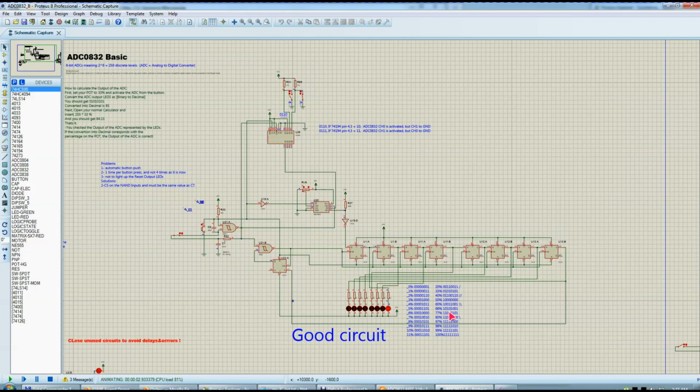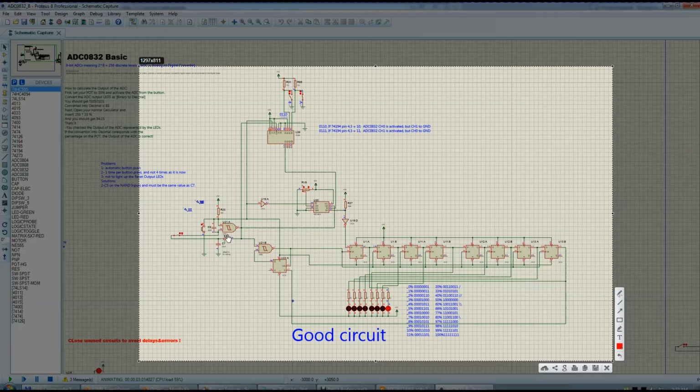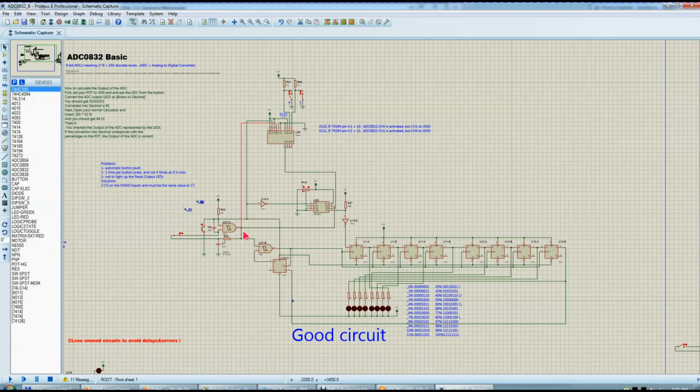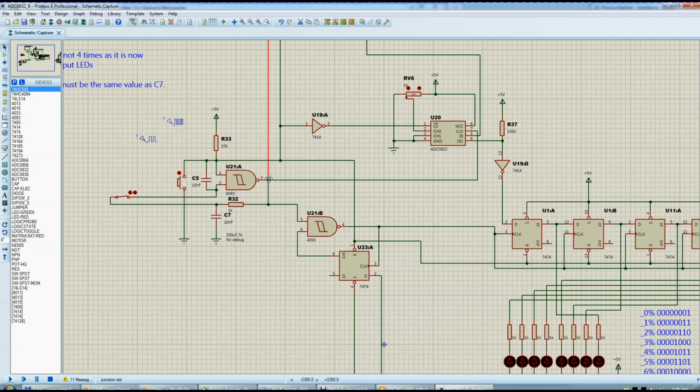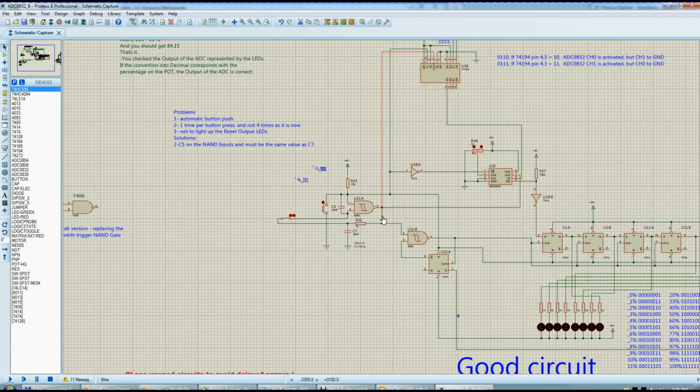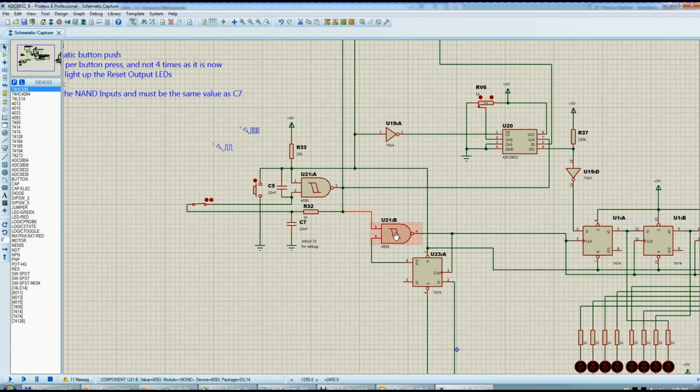So this is the timing circuit. Let me stop it because it's running, consuming too much power. This timing circuit is timing both this chip and this chip, only these two, not here. This is the line. You see the timing, this is the output of the timer, exactly on pin 3 here, in this node. It's going to this chip, and this line is going to that chip. Also a single line is going to one pin of this NAND gate.